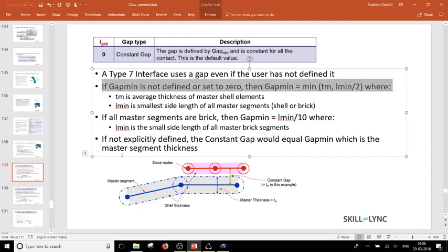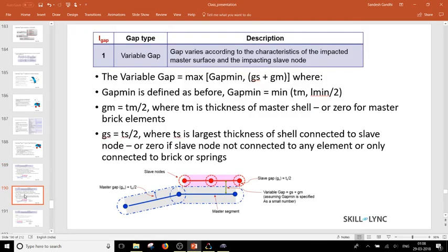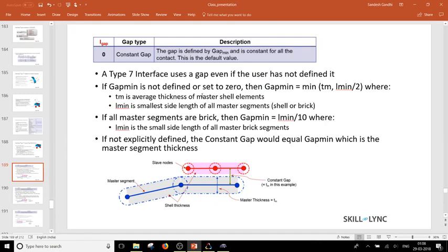So your gap min becomes 5 mm. And now this calculation over here is not really dependent on mesh size at all, but this gap min is dependent on mesh size. So this can become confusing because there was no gap min defined by the user, and that is why it had to stick to this particular comparison, and that could create a lot of issues.